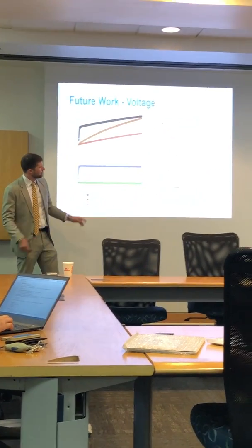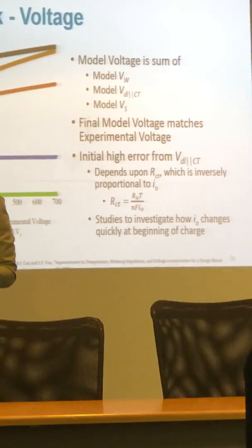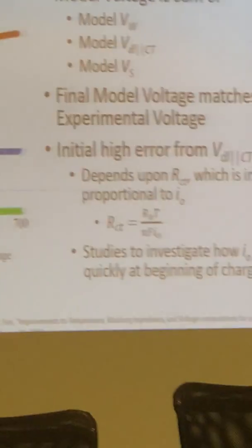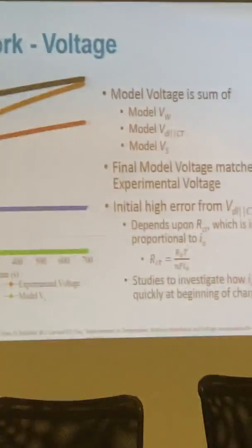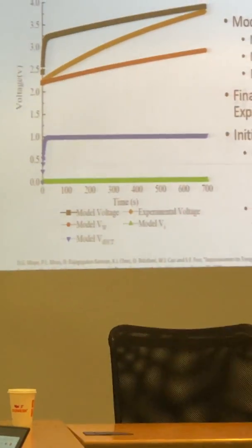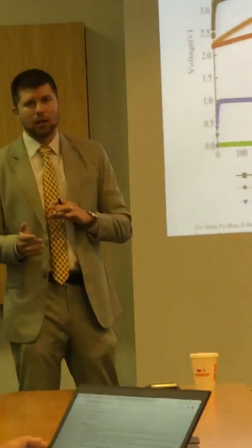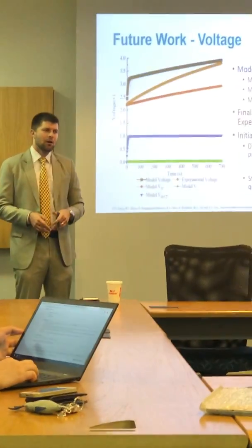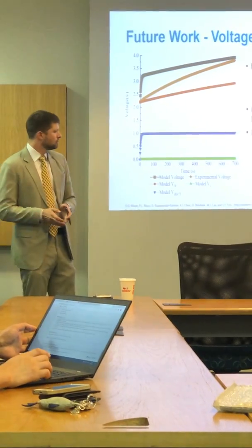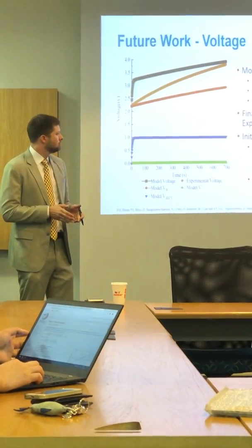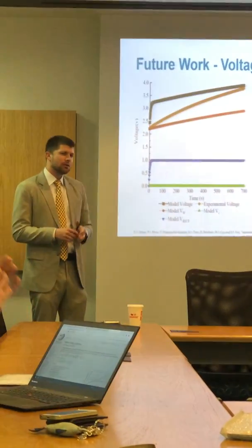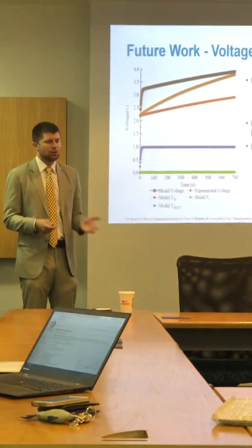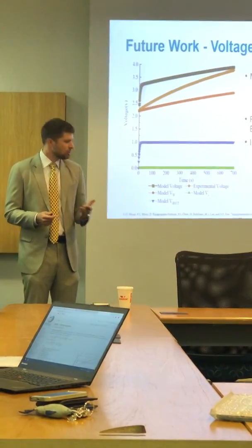Why is this? Well, the voltage drop across my double layer charge transfer RC element has to consider the voltage drop across my charge transfer resistance, which is a function of my exchange current. Now, that's this blue line right here. Exchange current levels off to a constant 10 to the negative fourth or 10 to the negative fifth amps per meter squared. But it starts out initially as 0. So just think about this, when the cell's not charging or discharging, there's no ionic exchange current.